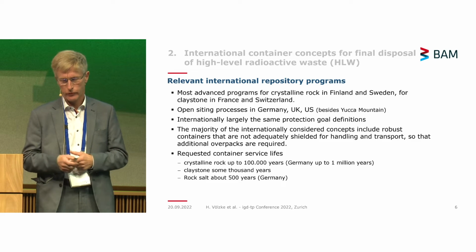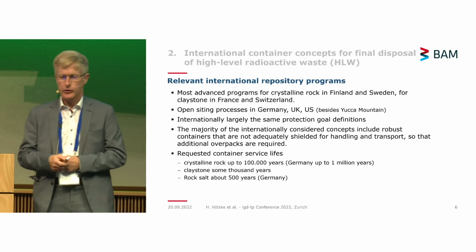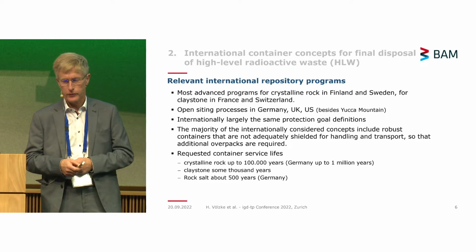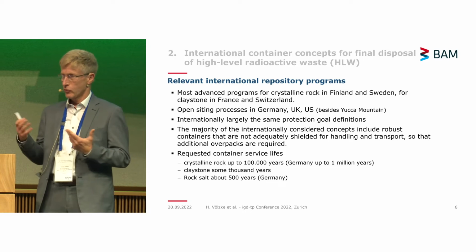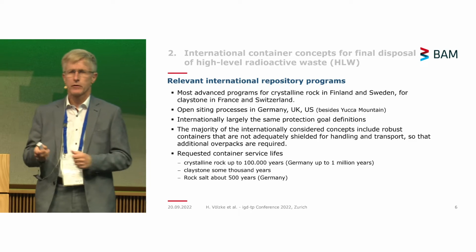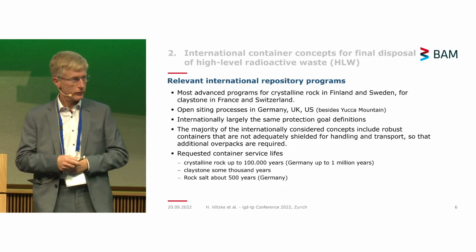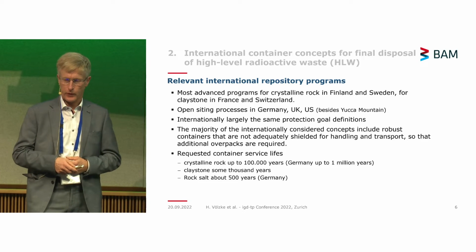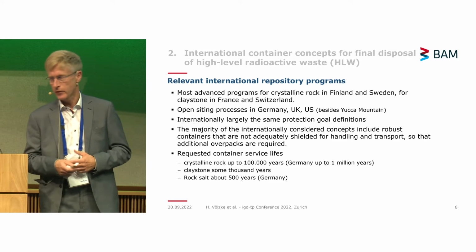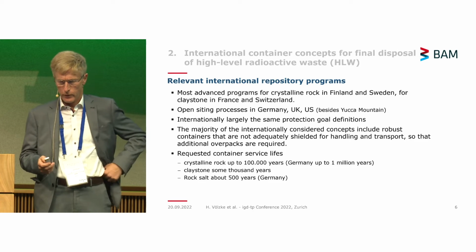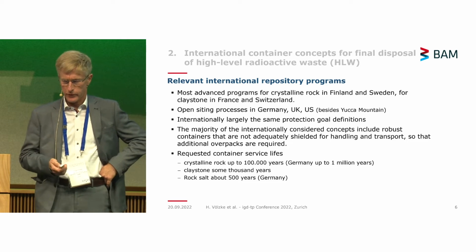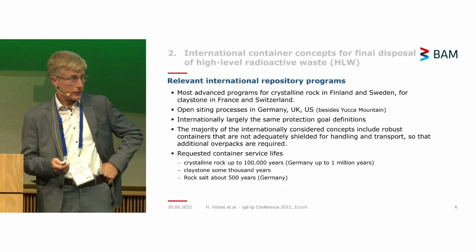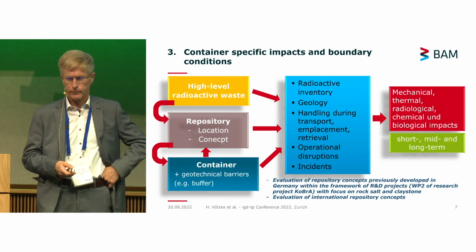Internationally, which is somehow logical, there are largely the same protection goal definitions, especially in the nuclear area. The majority of the internationally considered concepts include some kind of robust containers, but very often they are not self-shielding or not completely self-shielding, so they need additional overpacks. And requested container service lives, as already discussed here, are up to 1 million years or some 100,000 years, and for rock salt in Germany, the latest was about 500 years.